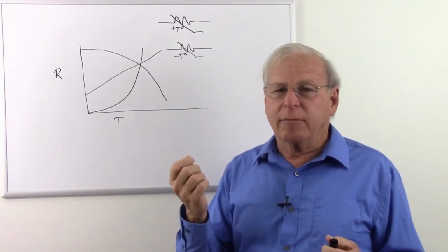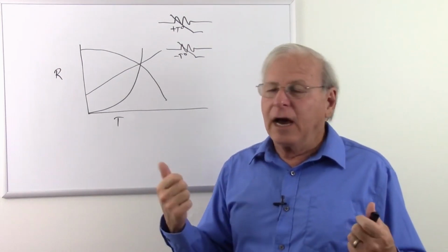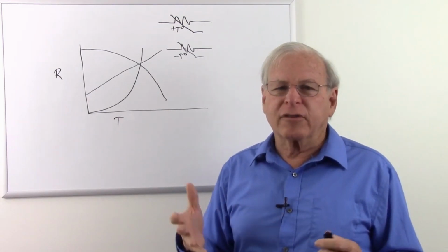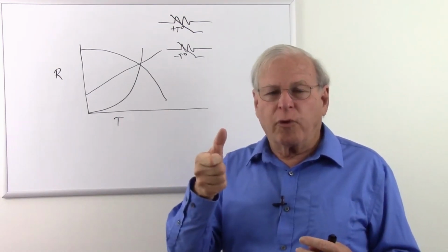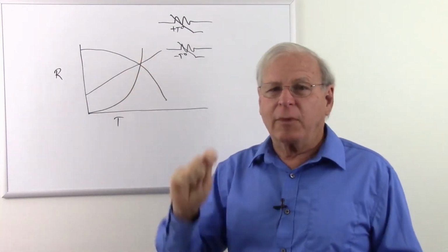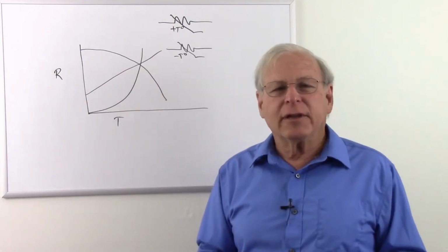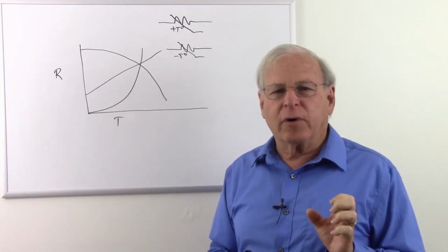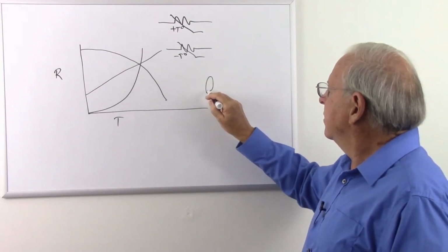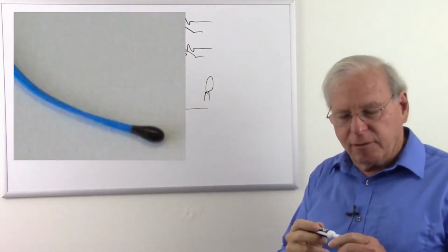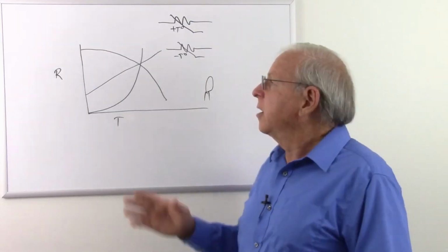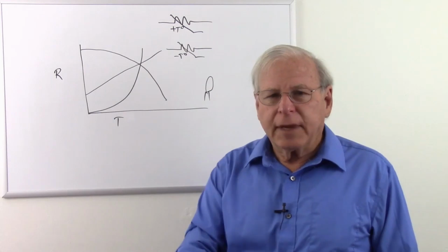You have a little electronic thermometer, wherever it might be. They're going to use often thermistors to measure the ambient temperature. This is not like the ones that you just point, which have an infrared sensor, but these actually respond to temperature. So if you stick a thermometer in your mouth, it's got a thermistor in there. Pull the CPU off of a motherboard in a computer, you're going to see a little glob in there, a couple of leads off of it. That's a thermistor to measure the temperature of the CPU. So that's the purpose of a thermistor.